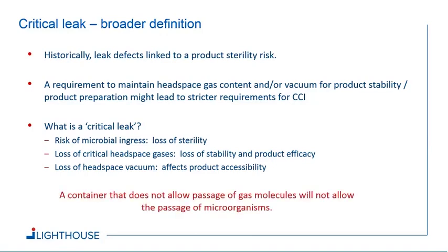And really, when you think about it, a container that does not allow passage of gas molecules will also not allow the passage of microorganisms. So if you can develop a CCI test method which shows that your container is gas tight, or at least is free of defects that allow for the free passage of gas, then this container will also be a microbial barrier.